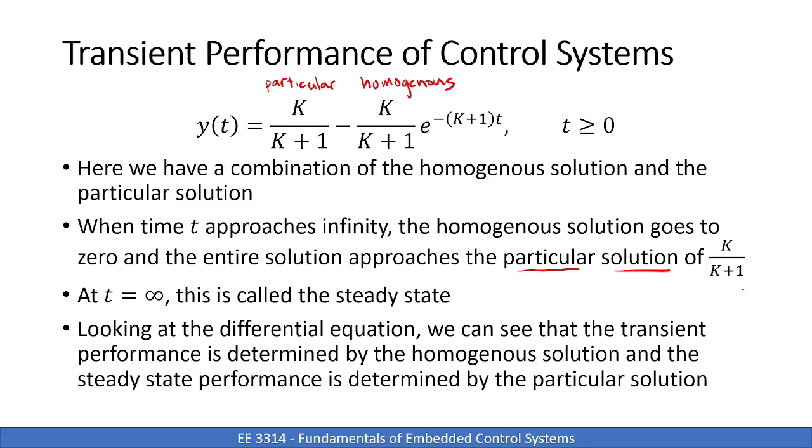So that's another example: if we do have some error, we can allow for our final value. That's really going to drive our control system design, right? If we have to be within 1%, then we know that for this type of control system, k would need to be 99. So it would be 99 over 100. Now that may have other ramifications that impact performance. There might be some trade-offs, but that's just one example.